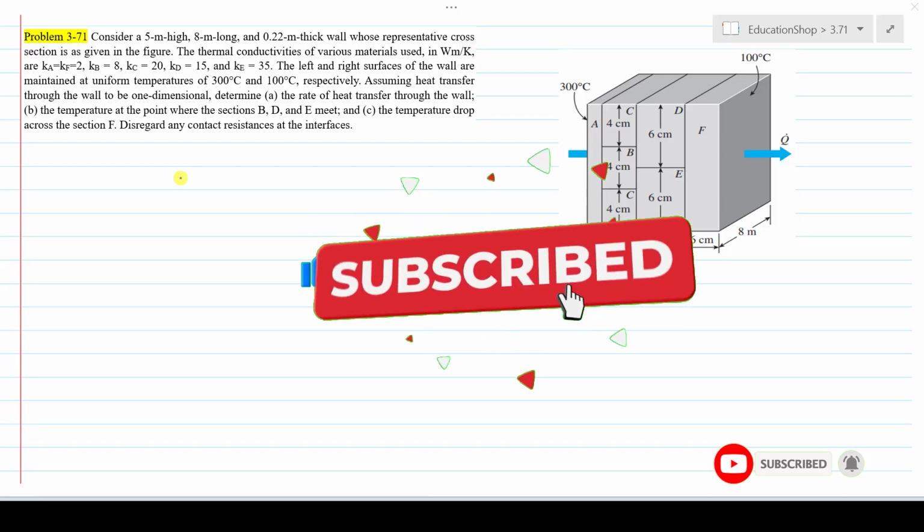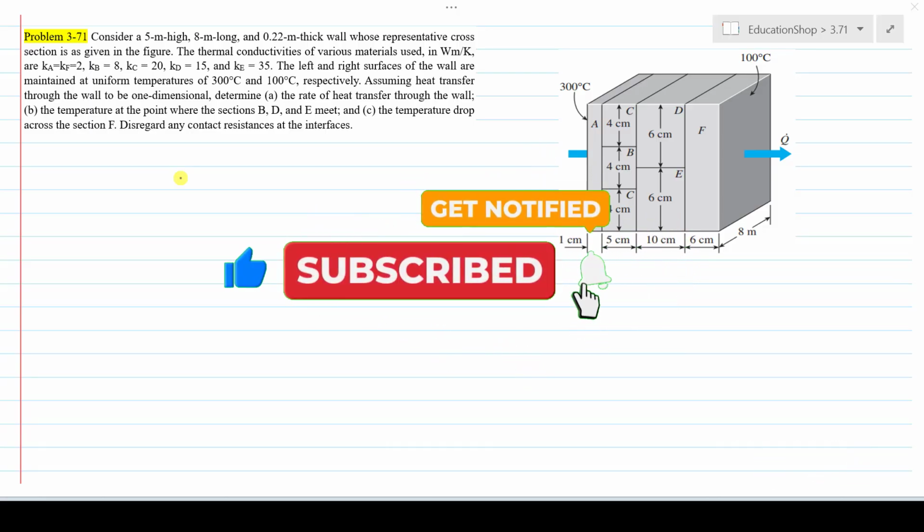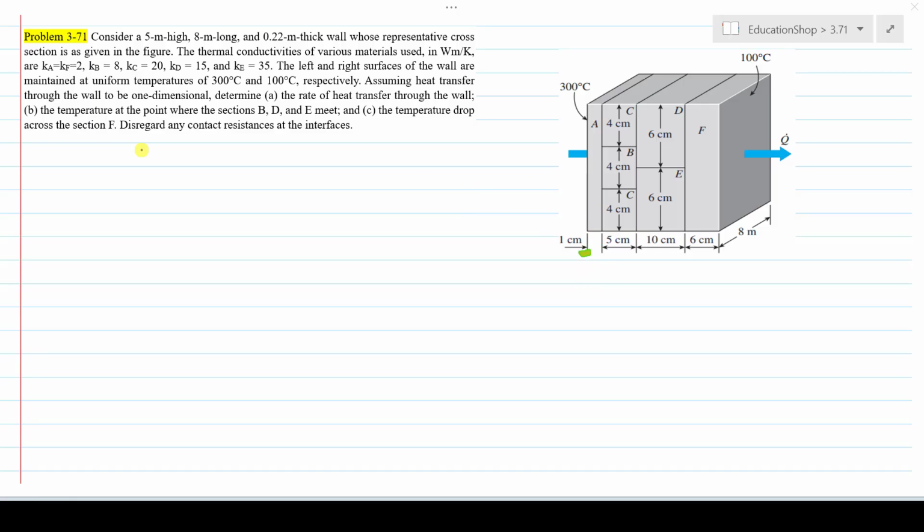In this video we will solve a very interesting and conceptual question from the heat transfer book by Cengel, chapter 3, problem number 71. Coming to the worded statement: consider a 5 meter high, 8 meter long and 0.22 meter thick wall whose representative cross section is as given in the figure. The thermal conductivities of the various materials used, in watt per meter Kelvin, are Ka and Kf equal to 2, Kb is 8, Kc is 20, Kd is 15 and Ke is 35.